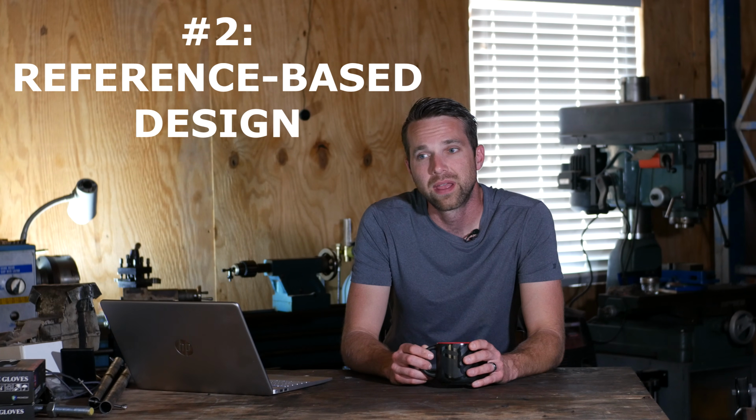Now, the second tool that you need to understand before jumping into top-down design is something called reference-based design and/or parametric design, I've heard it called. Reference-based design is a way of using geometric references, being planes, let's say sketches, axes, points, things like that, kind of more conceptual geometry, to then develop components and place them in an assembly.